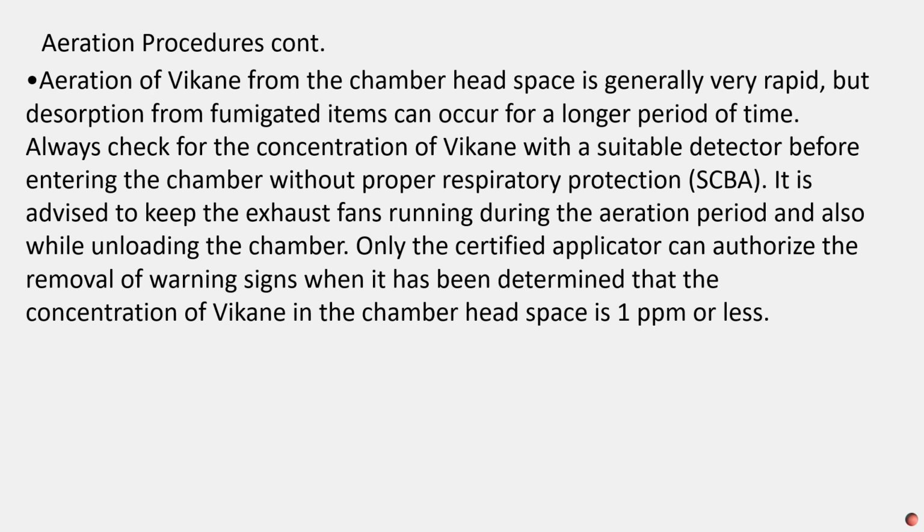Aeration procedures continued. Aeration of Vikane from the chamber head space is generally very rapid, but desorption from fumigated items can occur for a longer period of time. Always check the concentration of Vikane with a suitable detector before entering the chamber without proper respiratory protection. It is advised to keep the exhaust fans running during the aeration period and also while unloading the chamber. Only the certified applicator can authorize the removal of warning signs when it has been determined that the concentration of Vikane in the chamber head space is 1 part per million or less.